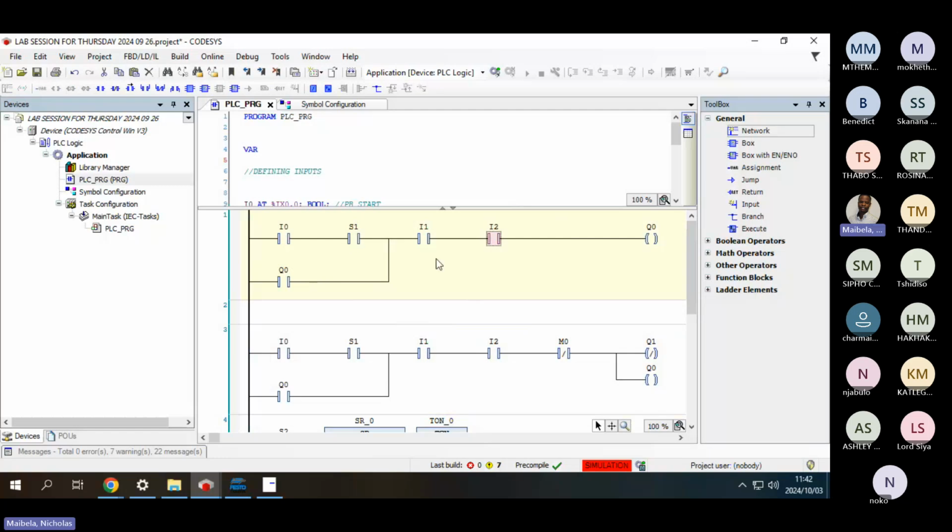Okay, yeah. So this circuit here, it's your stop-start circuit. As you can see, if you analyze it, it comprises a start button and a sensor. So these two here are for end position sensing, right? So as it is here, it will sense the retracted position, right? And then there you have I1, I2, which is your stop button and your emergency stop.